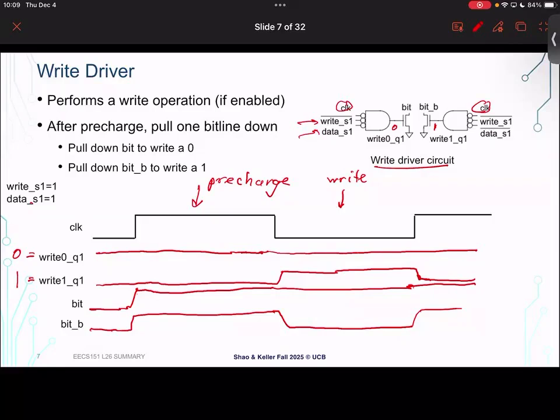There's lots of capacitance. And so in practice, you have to have really big driver circuits, really big buffers on the output of these AND gates in order to pull the bit lines down quickly. Unlike the dinky little access transistors inside the bit cell, which are pulling them down very, very slowly, this needs to pull it down very quickly so the write can take place. So you need to have big, big drivers.